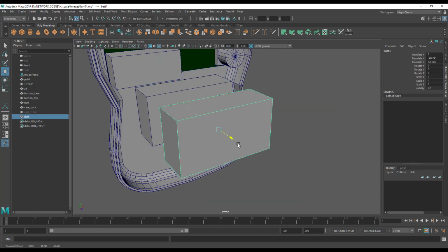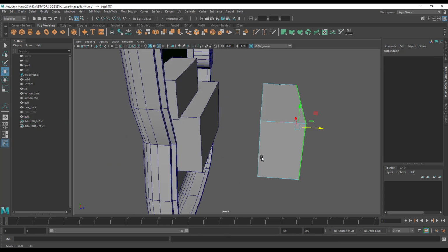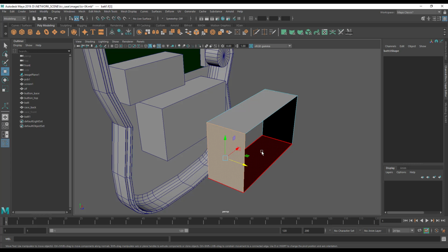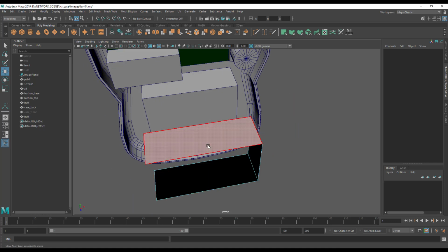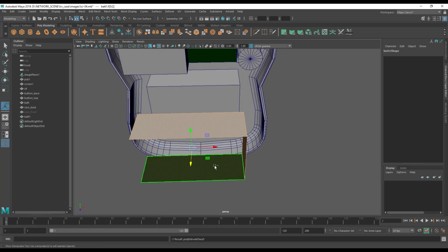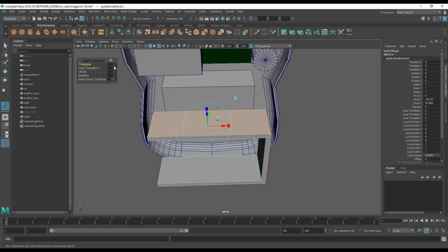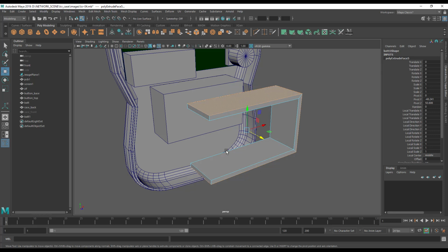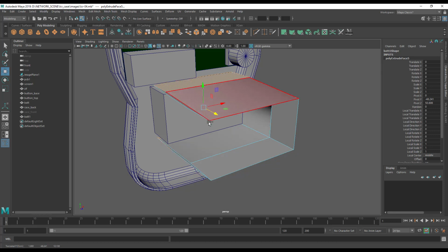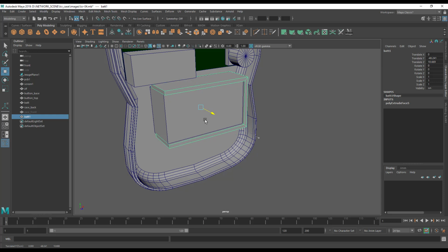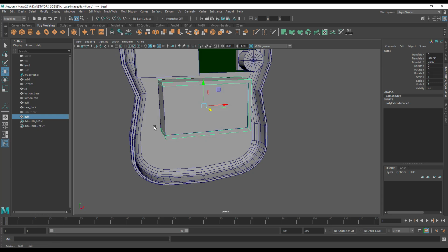So once again, let's Control Duplicate, same procedure, front face, back face, get rid of them, and this time get rid of this space, so we don't have anything here. We're going to hit Control E to extrude, and once again a thickness of 2 millimeters. So this now allows us to have, whoops, that's not a good idea folks, there we go. This now allows us to have a battery holder that's open at one end.